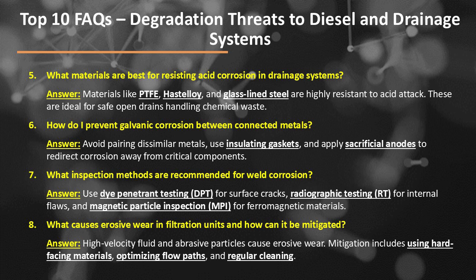Question number 8. What causes erosive wear in filtration units and how can it be mitigated? The answer is, high-velocity fluid and abrasive particles cause erosive wear. Mitigation includes using hard-facing materials, optimizing flow paths, and regular cleaning.